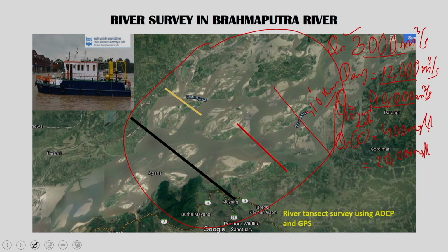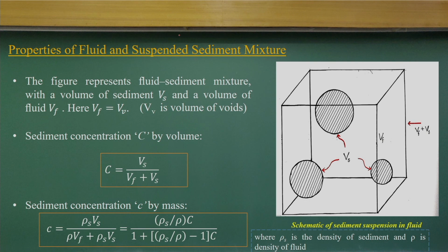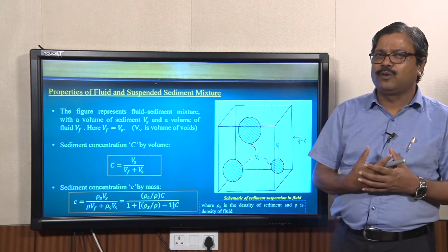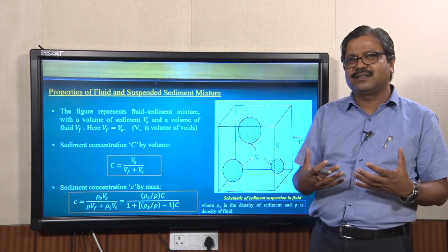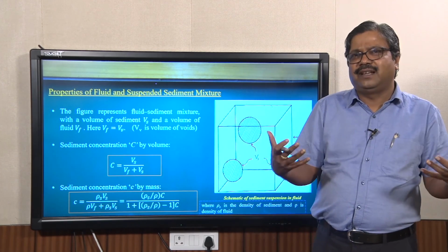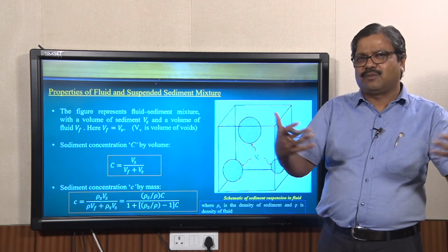All this process we try to understand with our basic knowledge of fluvial hydrodynamics. We will talk about more details. With this, the variabilities: what I mean is that the river doesn't carry just water flow, it's a mixture of the fluid and the sediments. So there is always sediment, except in very low flow periods, and the sediment concentration increases exponentially when we have a larger flood or event.